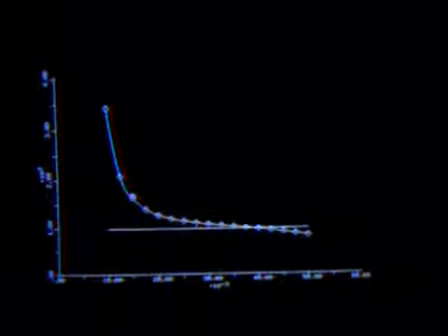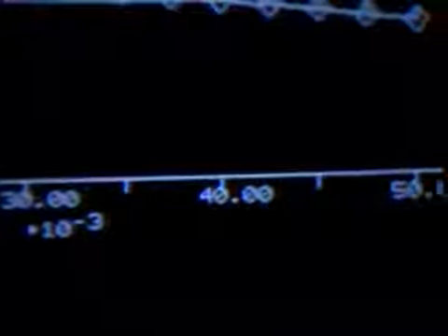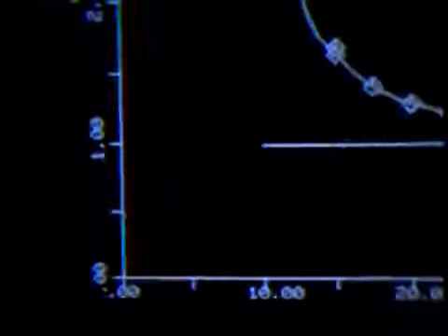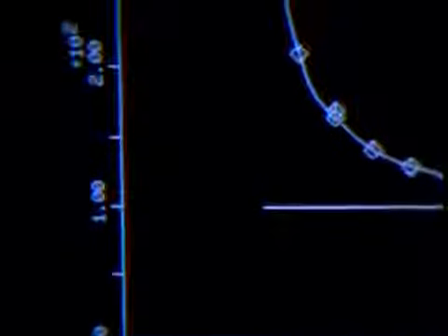Here we see once more the mesh we are using in the analysis. We will plot the stresses, and hence we can see the stress jumps along the horizontal symmetry line and the diagonal line of the plate. Here you see the stresses along the horizontal symmetry line. Tau ZZ is plotted. The horizontal axis measures distance along the symmetry line, and the vertical axis measures the stress values.